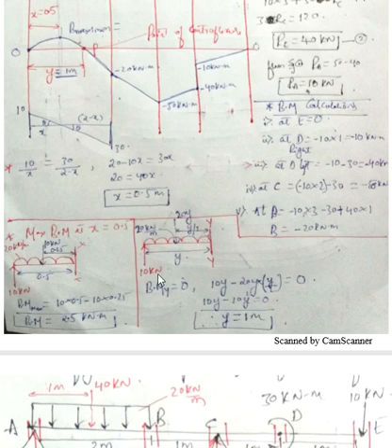Now when I take the bending moment because of these two forces with respect to YY, it should be 0. So bending moment with respect to YY equals 0. This force will lift the beam upward with respect to section YY, so the beam will look somewhat in this manner. So it is positive: plus 10 into perpendicular distance Y. Next, this force is 20Y, which will bend the beam downward. So negative: minus 20Y is the force, and the perpendicular distance is Y by 2.